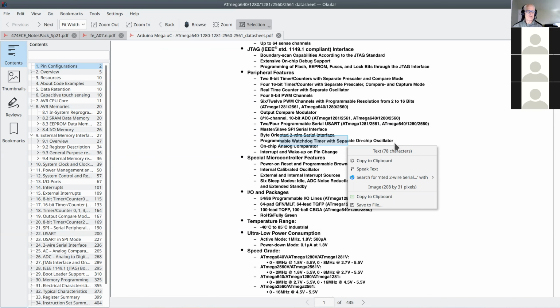That's not acceptable. So a watchdog timer is a clever thing, which is a hardware timer outside of the CPU, independent of your software, and it sends a message every so often to your computer, and your software has to respond to that message and reset the timer.